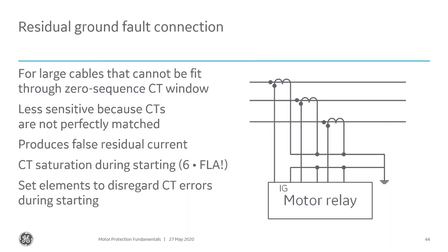So basically, I guess I should say C57, but the C57, C37 standards that describe these CTs basically say that during the linear portion of its curve, it produces 90% accuracy. Well, that means it could have up to a 10% inaccuracy. Well, 10% of that 1,000 amps is 100 amps. So I could have 10% inaccuracy, which might look like, if I ignore the fact that this is vector addition, 100 amps of unbalance just because of CT inaccuracy.